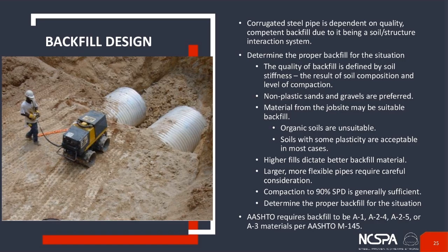And a lot of times the native backfill on the site are acceptable as long as they're not organic. Most of the time I'll refer to the geotech to look at those and make sure that they are acceptable. When we get into higher fills and larger structures, it's pretty self-evident that your backfills need to be a little better, whether they're rock, gravel, whatever they may be.